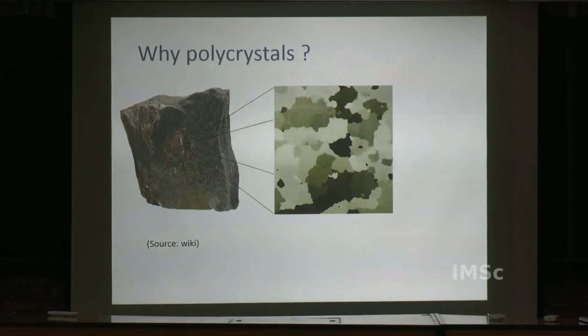But in the 90s, people found that at very small scale, if you keep on making grains smaller and smaller beyond some scale, which is let's say several hundred nanometers, it actually becomes softer. So you are making your grain small with the hope that hardness and yield stress will go up, but after you are down to some scale, yield stress goes down. And why does it go down? I don't think it's quite settled, and it's somewhat an open question, although people have a qualitative understanding.